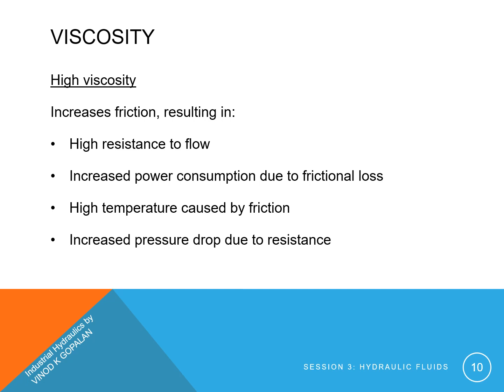Now, let us see what happens if the fluid viscosity is high. High viscosity increases friction, resulting in high resistance flow, increased power consumption due to frictional loss, high temperature caused by friction, and increased pressure drop due to resistance.